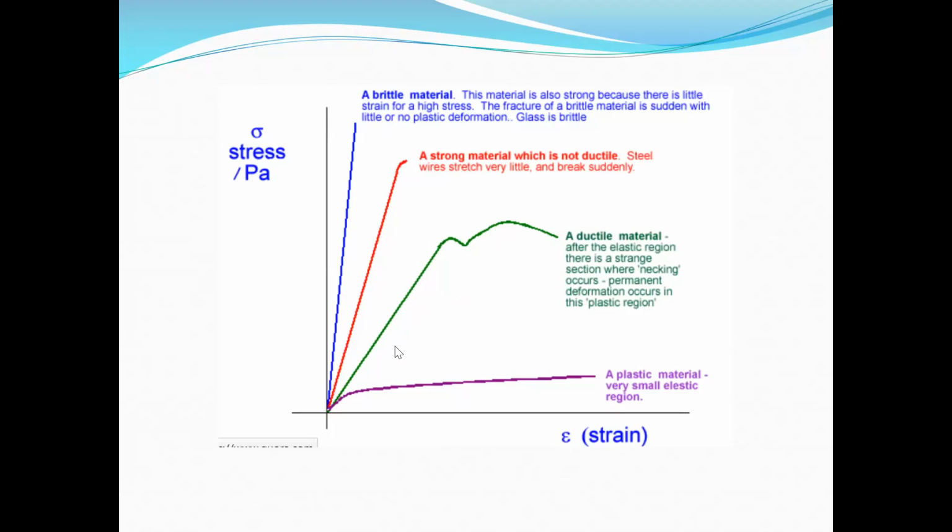This one is actually the ductile material, the normal reinforcement bar or rebar that we use in construction of buildings. So that is the standard typical curve. Initially, when the material is subjected to load, for example, a steel rebar is tested in the lab by fixing it in a UTM machine. We'll show the arrangement in later classes, and we'll also do the test in the laboratory, or by this time most of you have done it. So initially, when the load is applied, this is the elastic range, then this is the yield point, and then this is the plastic range.